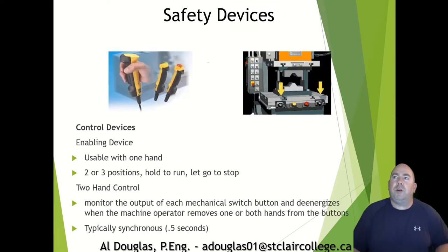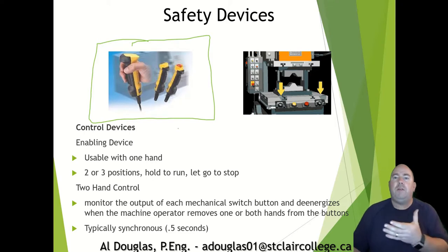And our final device we're going to talk about, these controlling devices, such as an enabling pendant. You'll see these on our robot cells in the robot lab. We have them on the teach pendant. You need to squeeze them, and you actually have 3 different positions to them. So if you picture you're squeezing this button, it has basically like a trigger to it.